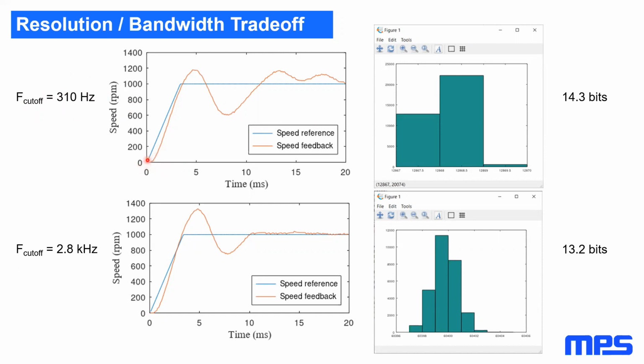lag behind, because during acceleration, by the way, I should mention that our window filter does have a speed state variable. So at constant speed, it doesn't have any error or any angle lag. It does not have an acceleration state variable. So this is where you'll see during acceleration is when we'll see this angle lag. So during the acceleration, we see a lag. We see an overshoot, and then it oscillates and comes back eventually down to its set point.